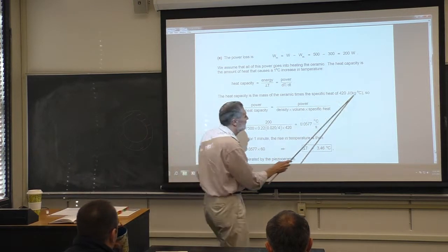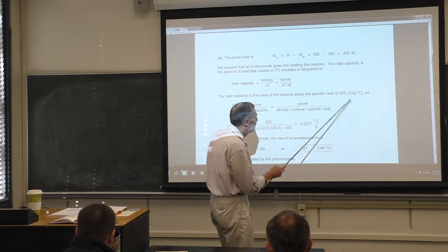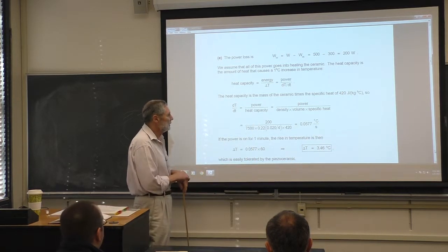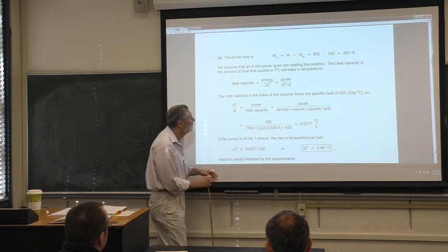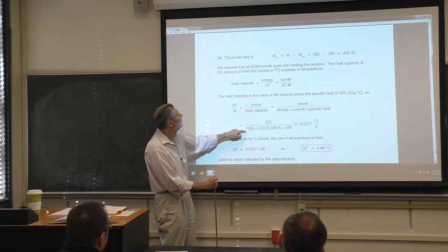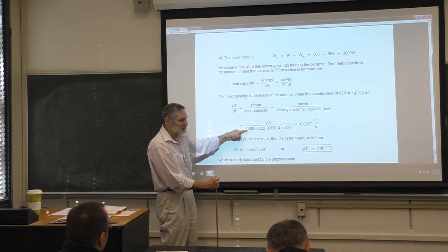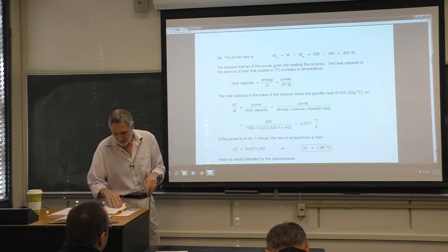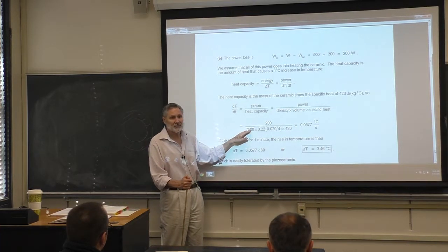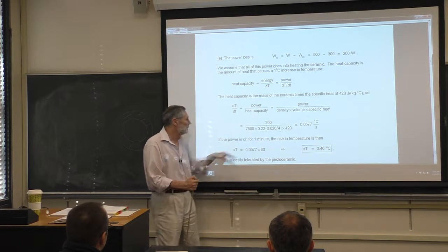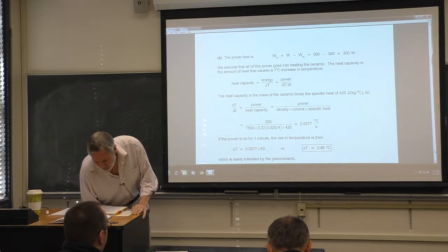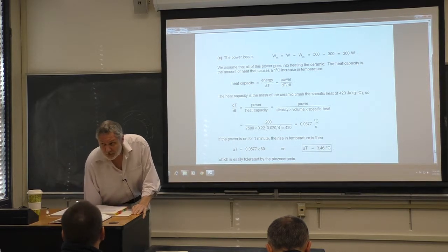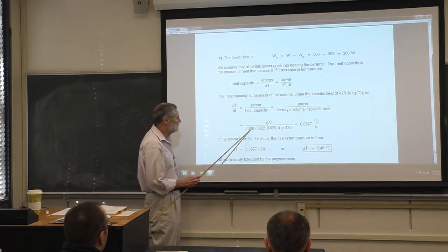This is just going to be per unit mass. This is a typical value. Apparently, we're given 420 joules per kilogram degree Celsius for ceramic. So we need to multiply by the mass of the ceramic, which is the density times the volume. We'll probably have to look this up because we're given the type. I don't think we're given the mass directly, but I can't remember. This is such a long problem. Yes, it's Navy type 1. So you look up the typical density.